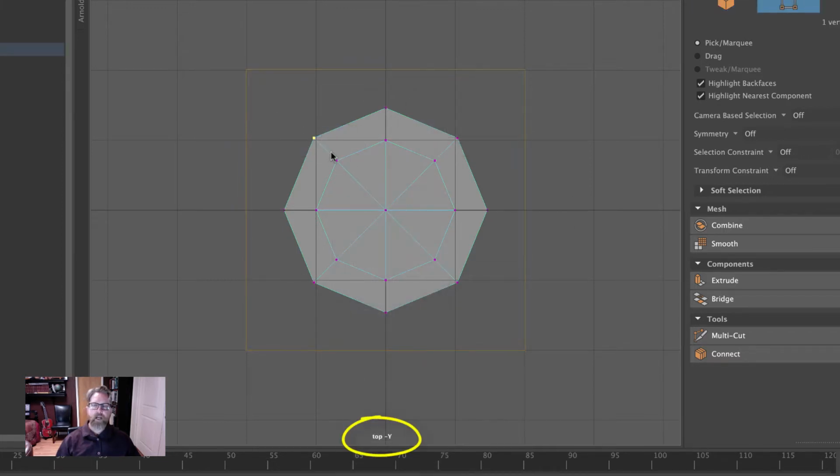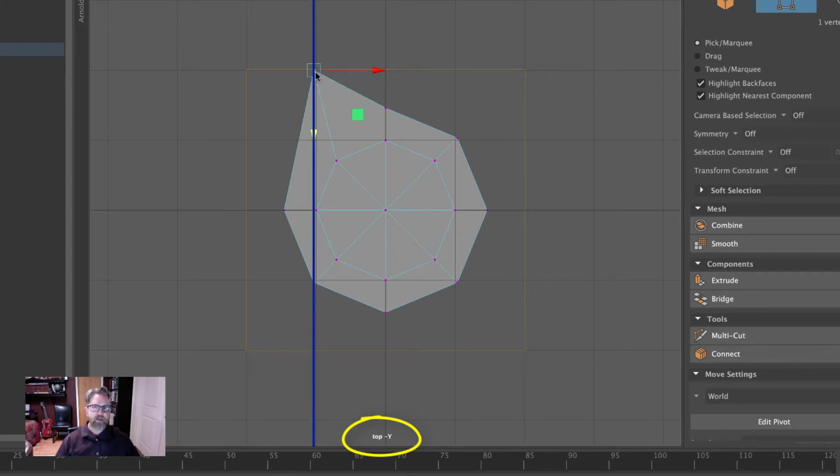And I just want to remind you in terms of snapping, I always recommend for introductory students that they click on what they're snapping to, that they don't click and drag what they're snapping. And the reason is, because if I come and try to pull this, I might accidentally hit one of the arrows, and now I'm constrained. So if I was trying to snap here and I accidentally touch this arrow, now when I hold down the X key and click with my middle mouse button, I'm constrained on that Z axis.